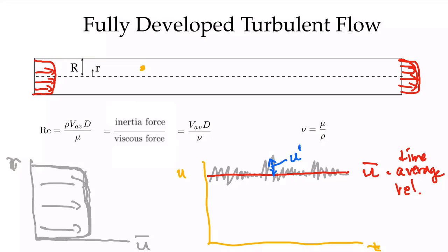And so we expect in the fully developed flow, the pressure forces are being balanced by the viscous forces because the inertia going in and out is the same. The velocity profile is the same in and out. And so if the shear stresses are higher, of course, we must have a higher pressure drop than in comparison to a laminar flow. And why does it come about that we have this?